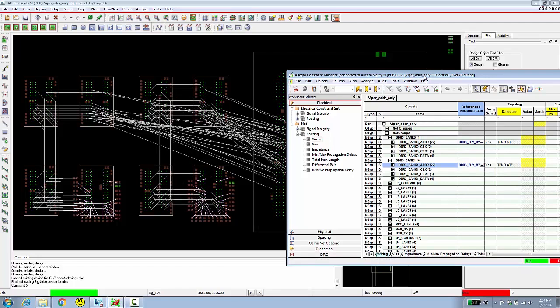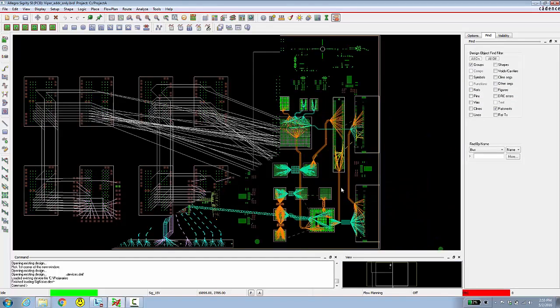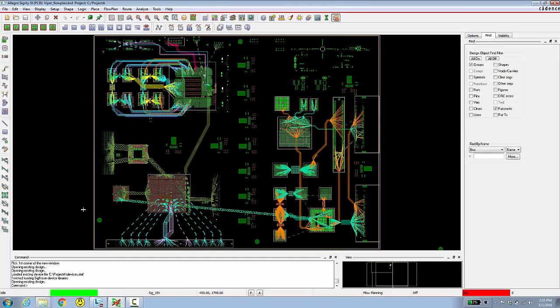Let's fast forward a little bit and take a look at the design after flow planning is finished. This certainly gives a better sense of how all the major routing will take place. The appearance of the bundles are different based on several factors. Coloring can indicate a default bundle, or one where the etch is limited to a specific layer. In other cases, a bundle with a crosshatch or dashed appearance was auto-generated based on net groups in the design, whereas solid-colored bundles were generated manually.